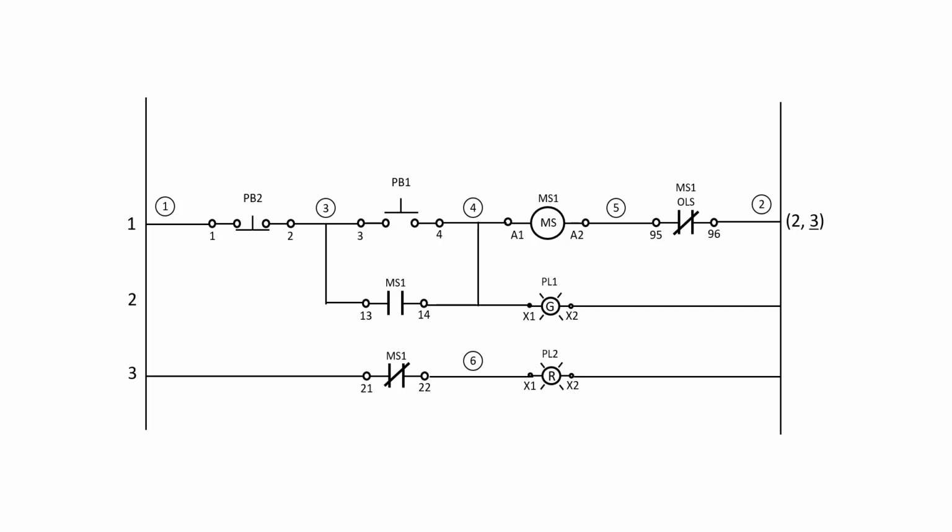In the case of inputs, we'll need to wire the push buttons, both PB1 and PB2, as well as a normally open auxiliary contact from the motor starter to provide positive feedback about the motor's state. We will not need to wire the normally closed contact, as the logic of the normally open auxiliary contact can be inverted with our PLC's logic. Additionally, the normally closed contact from the motor starter's overload relay will be hardwired in the output circuit, not as an input to the PLC.